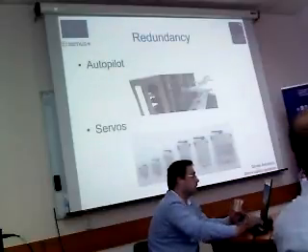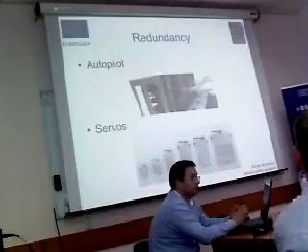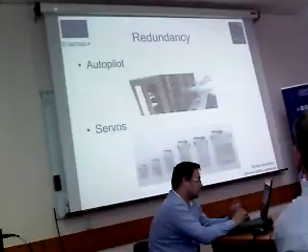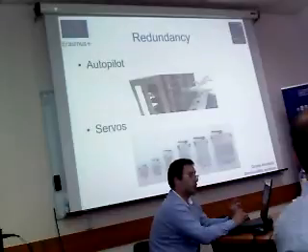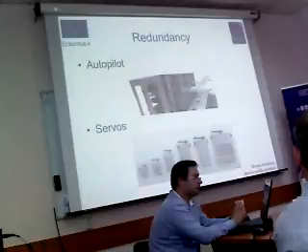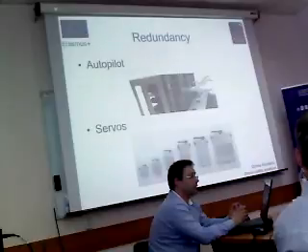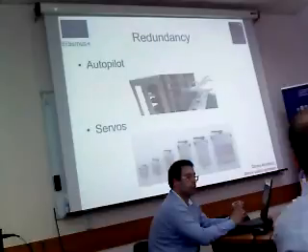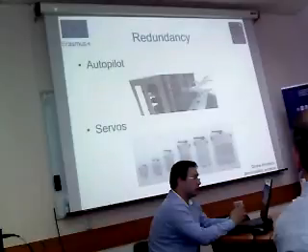And also, the common use of servos in unmanned aircraft is managing the control surfaces, and failures can happen there. So redundant servos also have two redundant input buses in order to give them higher reliability. So due to this redundancy, it's possible to avoid critical failures in a UAV if one of the internal buses of the control system fails, or if the wiring between the control system and the servo is not performing the expected task. So we would have a second line of defense to maintain the navigation with no incident.